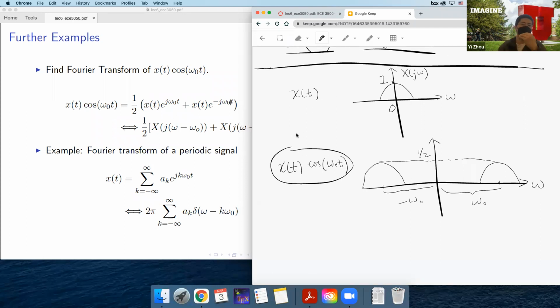The operation that we are doing is simply multiplying the signal by a very high frequency cosine signal. And this Fourier transform property tells us that if you do that, then the spectrum is simply copied and shifted to a higher frequency band. So the signal still remains the same, but we're just moving it to a higher frequency band.